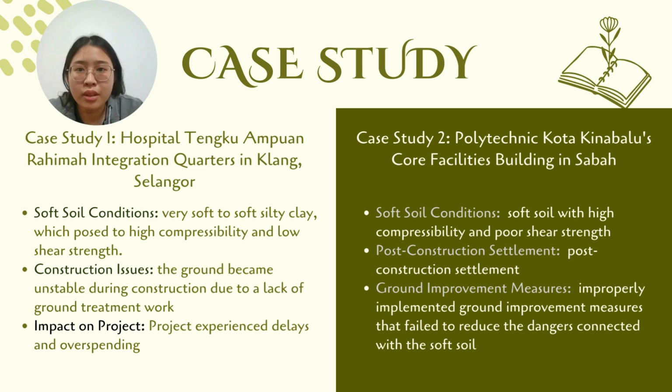So to deal with the reality, let's look at two case studies related to soft soil issues. The first case study is Hospital Tengku Ampon Rahimah Integration Quarters in Klang, Selangor, which has a soft soil condition of very soft to soft silty clay, posing high compressibility and low shear strength issues. This causes construction issues of unstable ground during the construction due to the lack of ground treatment work, and this has brought the impact of project delay and also overspending.